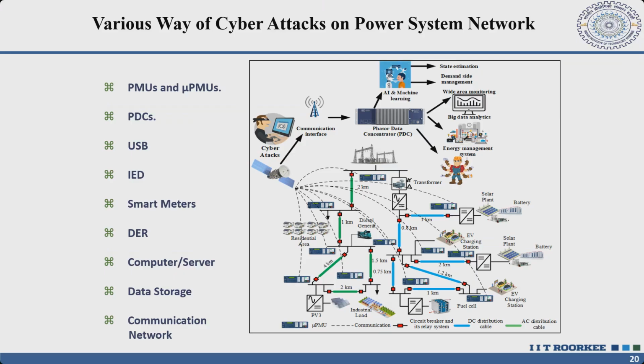So we, as we are paying the bills, have the block rate tariff, where we have the number of units consumed multiplied by the time, right, hours. There the company has the two-part tariff. They have this running cost, how many units they have consumed multiplied by the hours, plus some fixed cost, right? The fixed cost is calculated based on the contract demand.